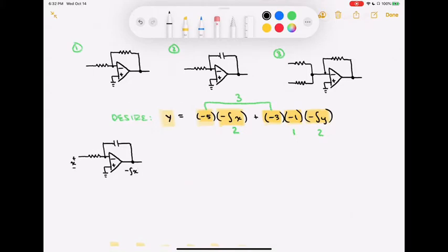I do think it's worthwhile when you're drawing out these circuits to go ahead and label the output of each op amp so that you can follow along as to what is being done. We know that that integrator output is going to be working together with that summing node. So I'm going to have to go through a summing node. The output of this first integrator is going to be going into a summing circuit, which I'm going to later combine with some of those output terms.